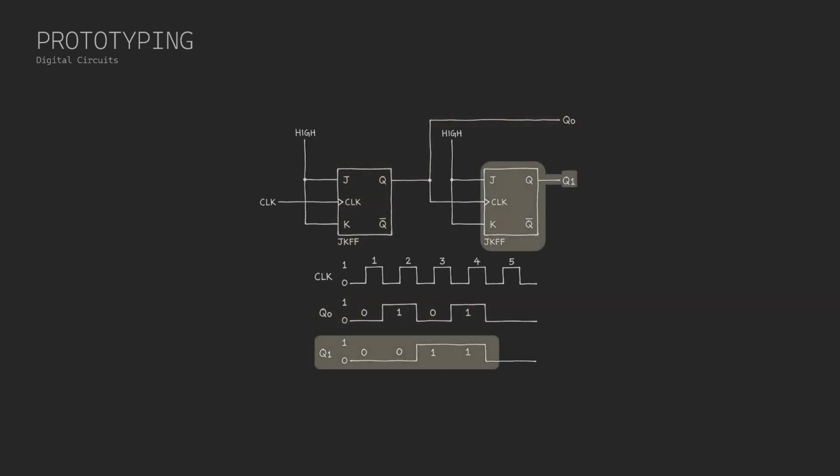The second flip-flop, the most significant bit, only toggles when the first flip-flop changes from 1 to 0, creating a ripple effect. The outputs Q0 and Q1 will have values 00, 01, 10, 11, and come back to 00, and then it repeats in the same fashion sequentially.